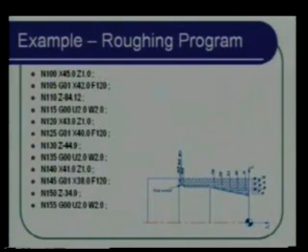Now all these coordinates are obtained from the CAD, and notice when I wrote this program, somewhere I am using the absolute coordinates and somewhere I am using the incremental coordinates. So it depends upon the convenience in avoiding some calculations. So that completes all my roughing cuts.